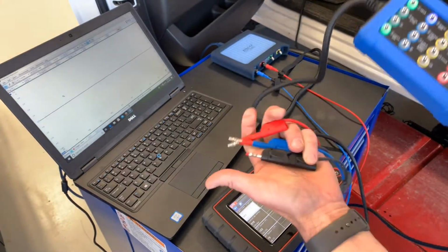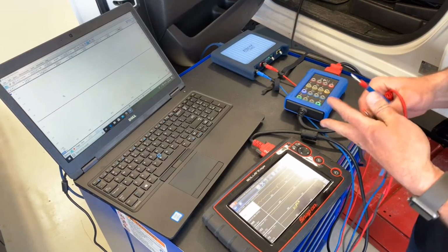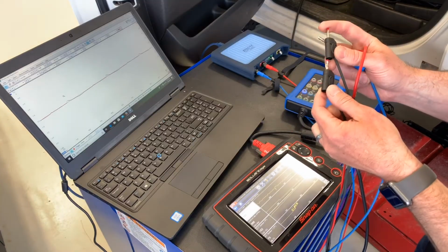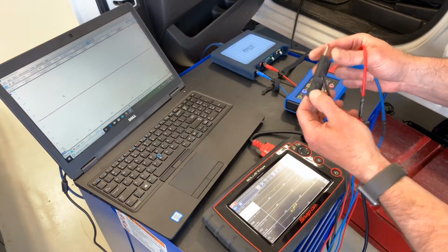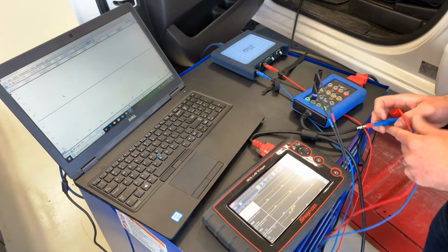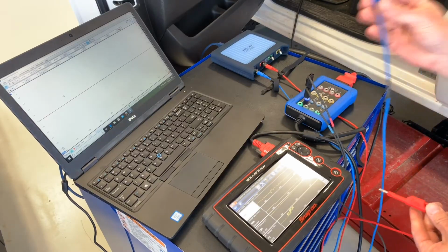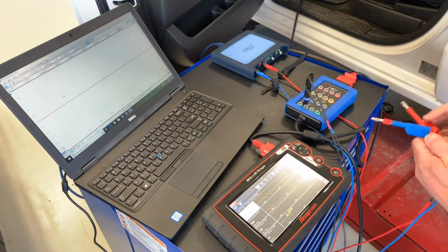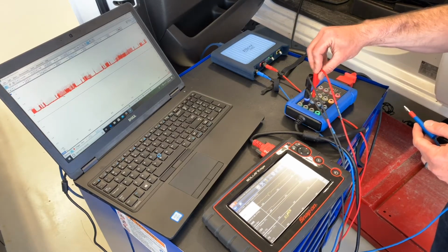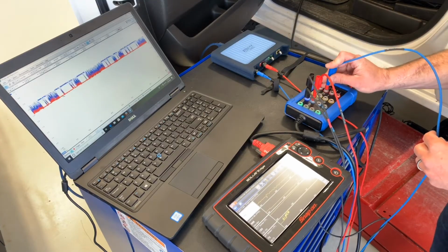And so if we start with that, I've got 2 channels going on my PicoScope. I've got both my grounds just stacked together. Real nice thing about PicoScope connections here and a lot of scope connections, I can piggyback those. And so then I'm going to go to just pin 5, my signal ground, leave that connected as my reference. And then my blue is my A channel, red is my B channel. I'm going to put my A on the high side of things, which is pin 6, and then my B on the low side, which is pin 14.